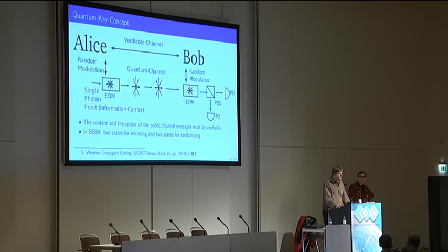So how do you come across this? No, I mean, you use an avalanche diode for detecting this photon. Yeah, but you can't detect one single photon with an avalanche. Yeah, but you don't have one photon then, because this type of detector does not have single photon resolution. It depends on what kind of avalanche diode you use, but there are avalanche photodiodes that are used for single photon detection. I'm very sure that there are.